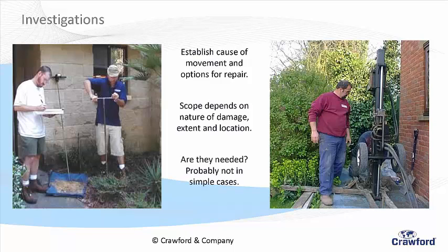They really struggle with desiccated clay. Do you know why they might struggle with that? Where's my sample of clay going? It's hard. Have a look at that. You try and auger through that. Very hard. So there's the perverse thing about this. The clay that we're really interested in, we struggle to investigate.